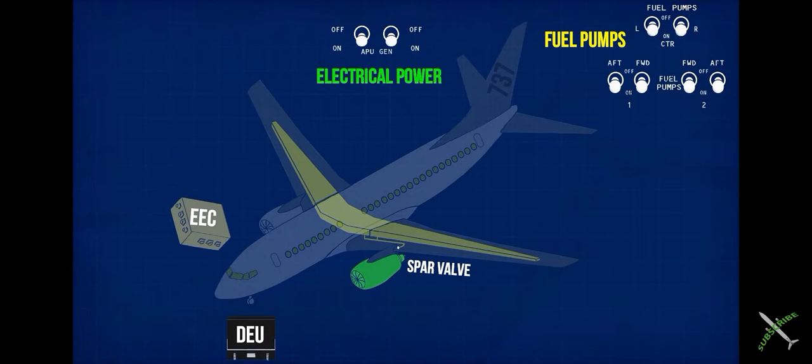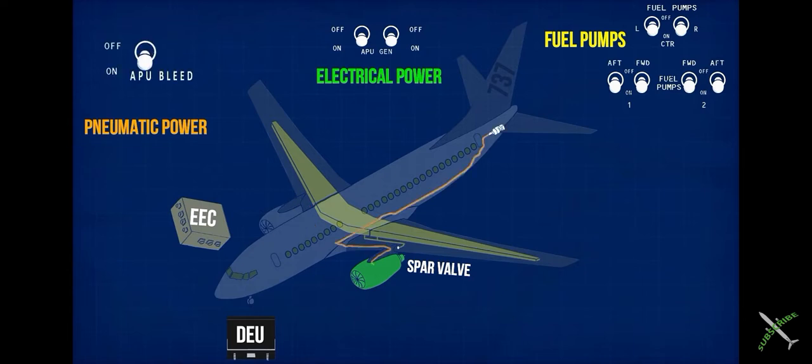In order to crank the engine, pneumatic power is required. Three sources of pneumatic power can be used: by connecting an external jet starter unit, from the other engine if it's running, or from the APU, which is the standard practice. Ignition switch position has to be changed.